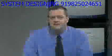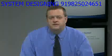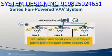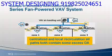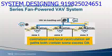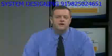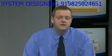We'll use a series fan-powered VAV system to illustrate the calculations in our example. In this system, one air handler brings in outdoor air at a central location and mixes it with recirculated air from all the zones. In addition, each fan-powered VAV box recirculates air from the ceiling plenum, providing a secondary recirculation air path to consider. Standard 62 gives you credit for the unused or excess outdoor air that recirculates, both centrally and locally.